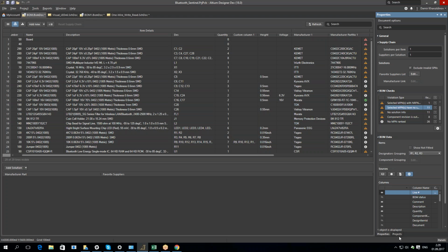Another change that we did in 18 is related to ActiveBOM, but just for you to know, it was a huge effort on refactoring the internals of the BOM generation. So from now on, we have a unified BOM engine that is being utilized by ActiveBOM. With this new engine, we were able to do many changes targeting performance. And that, I believe, was the most voted bug crunch related to bill of materials: the performance of BOM generation.